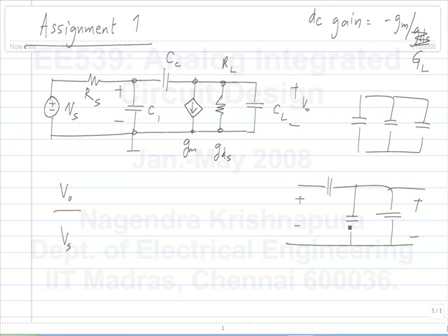The only thing you can say safely is that it's not more than 3rd order. But by looking at it a little bit, perhaps you can say it's a 2nd order system, because you have one loop of capacitors, and if you know the value of voltages across these 2, you can find out this one. But whether this itself is independent from this, it needs a bit more analysis. But in this case, it is 2nd order. That's the answer. Okay.